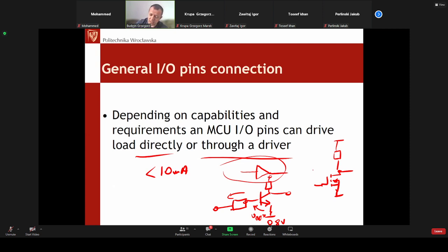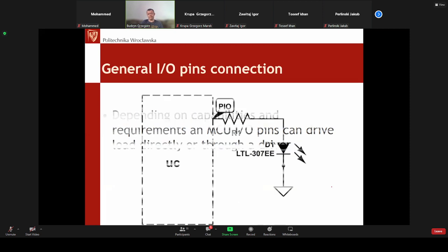And to be honest, here the resistor does more harm than good in case of MOSFET, because the series resistor slows down the switching of the MOSFET transistor. So for bipolar, a series resistor. For MOSFET, you connect it directly to the pin to form a driver, or you use a buffer for this purpose.